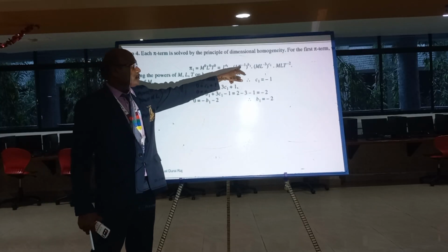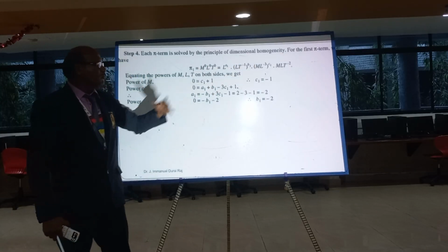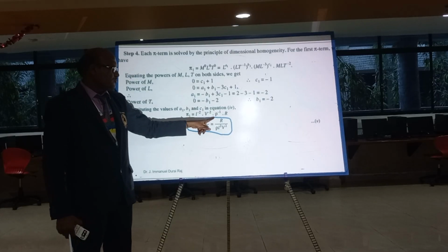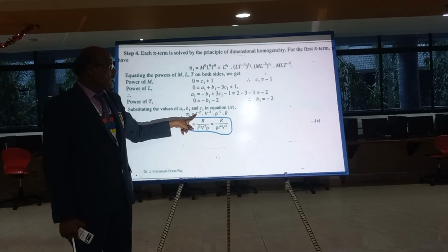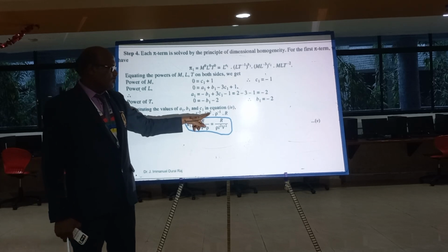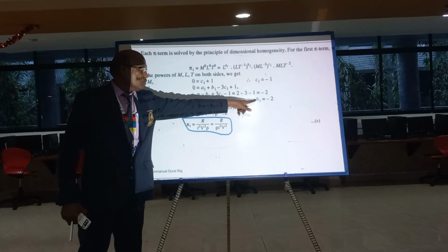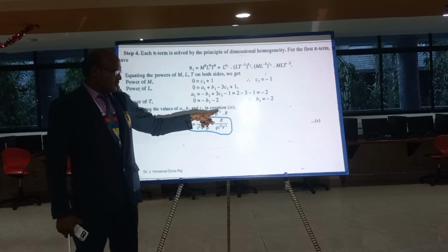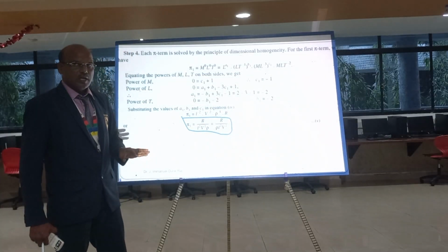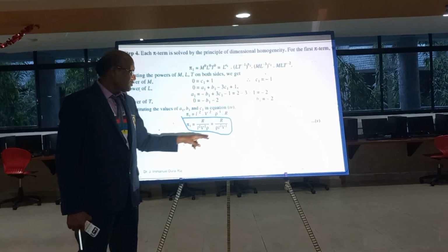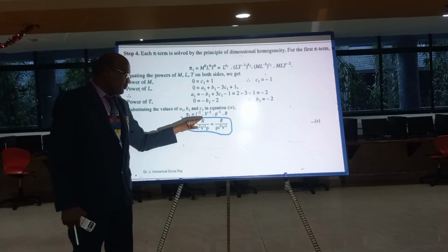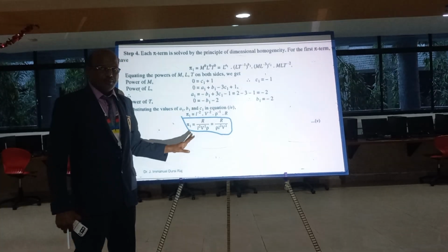Substitute these values directly into L, V, rho. Instead of dimensions, we know what L, V, rho are. So directly L power a1 minus 2, V power b1 minus 2, rho power c1 minus 1, and write R as it is. Okay, you can write a relation like this. So now you can find the relation between resistance and these parameters.